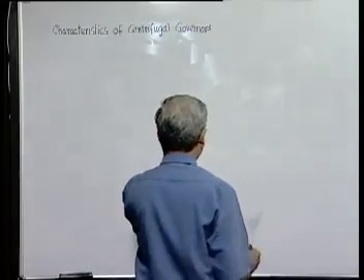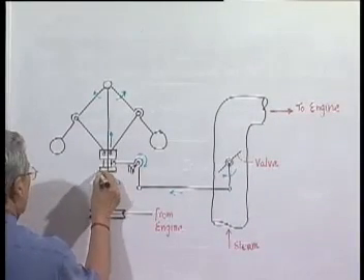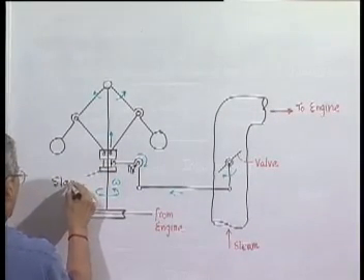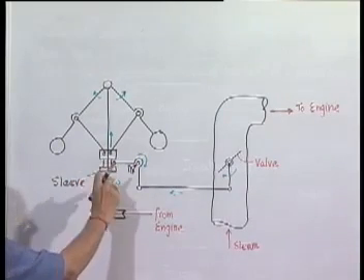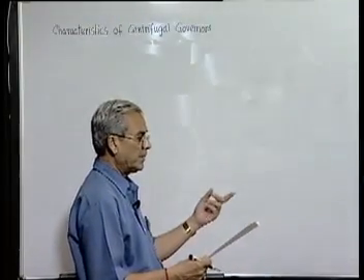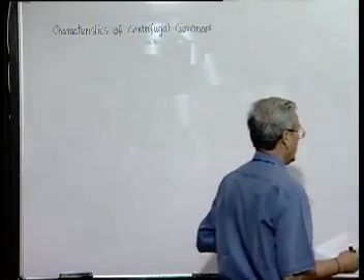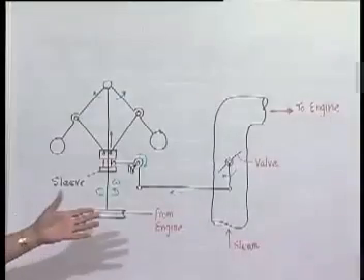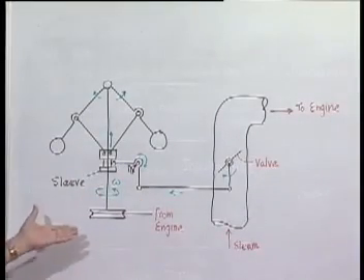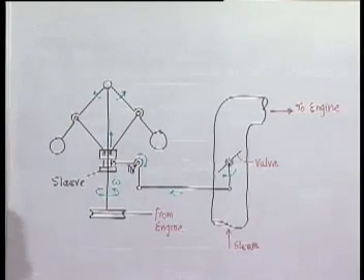Now one point is that the sleeve, this is the sleeve, actually controls the mechanism to operate the valve. The sleeve will be at the lowest position where the engine develops maximum power. Next important thing is, if the load is suddenly removed, the sleeve should reach its top position. That means it should change to a high speed situation very quickly. It should not be sluggish.